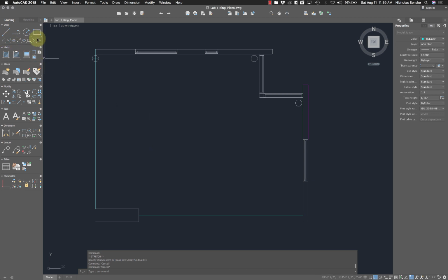There's a couple different ways to do that. The easiest way is to go over to the rectangle tool, and it says specify first corner. So I can just draw a corner, and then it says specify the area or the dimensions of the rotation. We're going to go D for dimensions and the length of the rectangle. We know the desks are 30 inches by 60 inches. So we can do 30, because the units by default are inches. So 30.